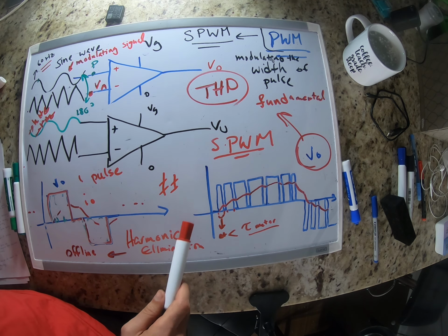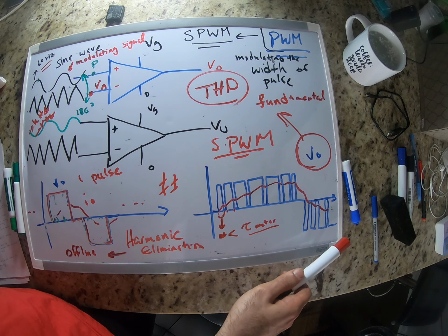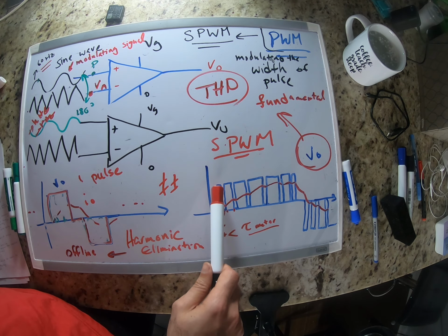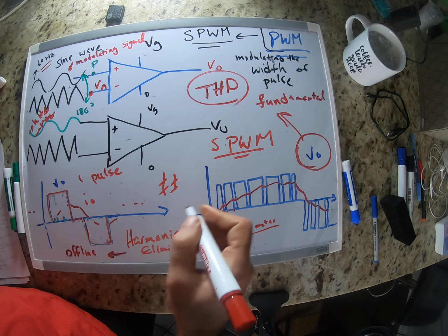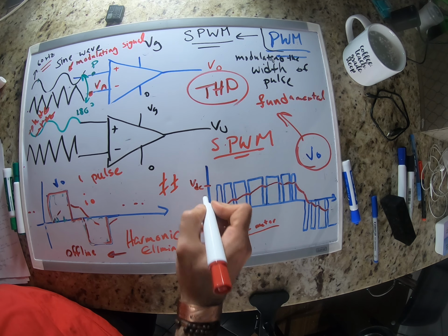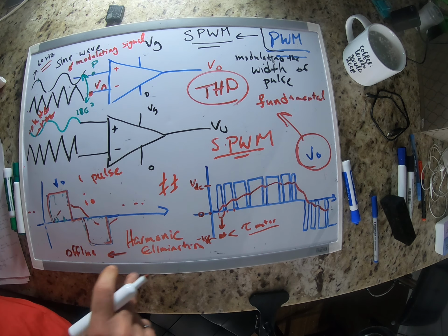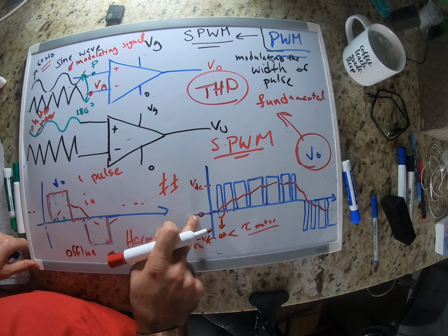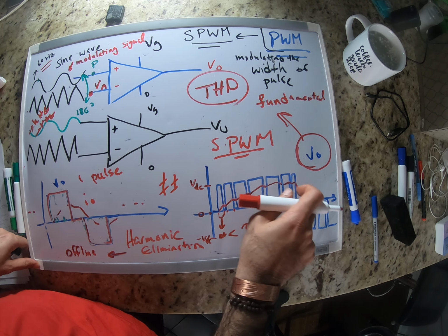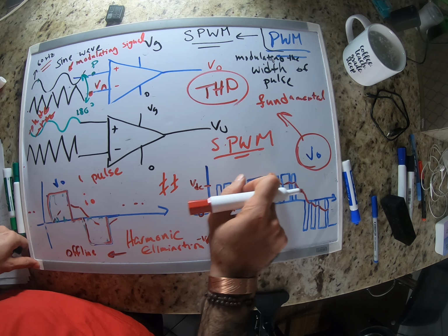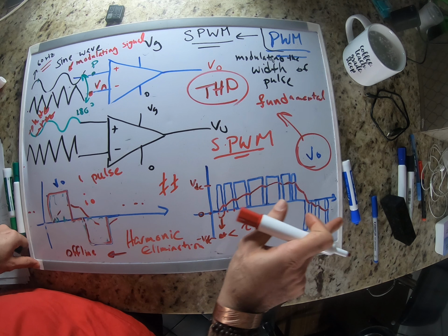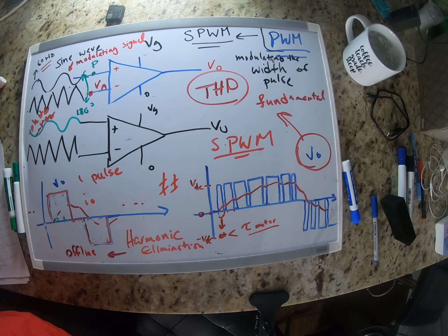That's very easy and basic to understand: how, using DC voltages, where we only have two levels of voltage, VDC and negative VDC, actually three levels with zero, using only three DC voltage levels, we create a signal that creates an AC current for us using PWM. And if you use PWM, your harmonics are going to be smaller.